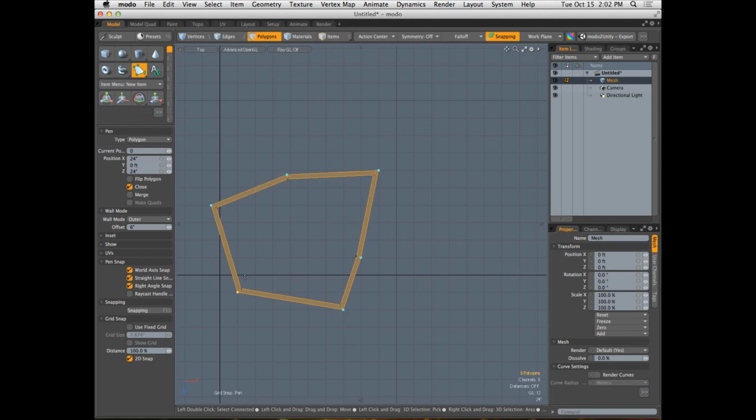Right angle snap is going to give you those little right angle indicators in the corners of all your edges, which is pretty neat. I don't seem to be. I'm getting a line. But I'm not getting the internal square, the right angle snap. Yeah. And I went into F11 and it's checked. It's checked to grid snap. So it's only something that you're going to see while you're clicking down with your mouse cursor.